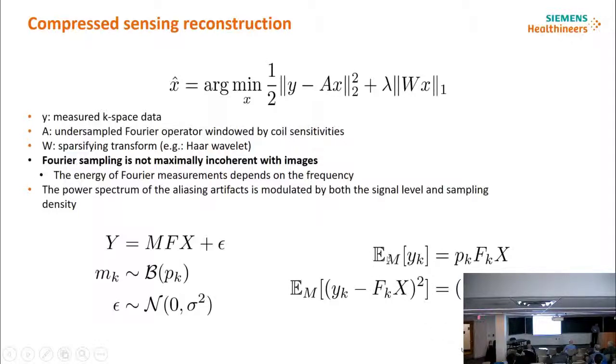So it's not directly what you get for one single mask, but it gives you a pretty good idea of what you would get in the wavelet domain if you start binning frequencies together. So the probability density is going to act as a filter on the mean that you get out, which means that if you sample with a variable density, your compressive measurement is going to have a filtering effect on the image that you get out.